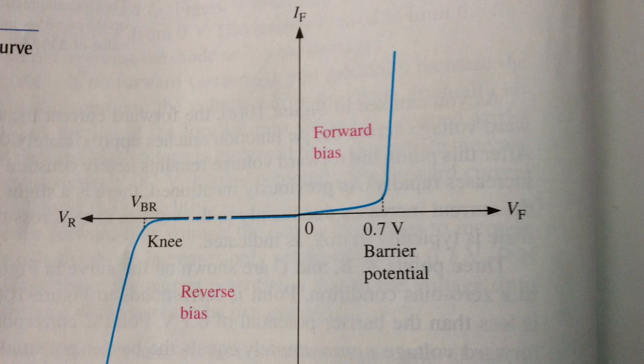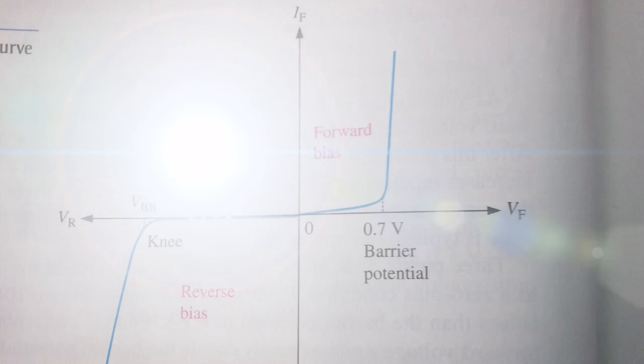When the applied bias voltage is increased to a value where the reverse voltage across the diode reaches the breakdown value, the reverse current begins to increase rapidly. As you continue to increase the bias voltage, the current continues to increase very rapidly, but the voltage across the diode increases very little above VBR. Breakdown, with exceptions, is not a normal mode of operation for most PN junctions.